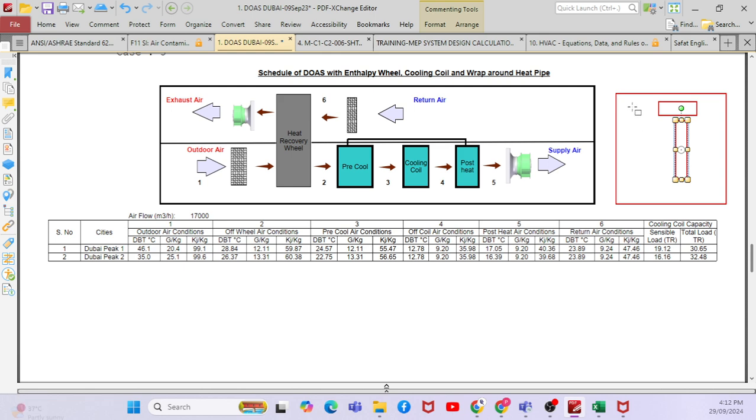Clear, right? Now I'm going to take out some of the air and supply fresh air. So to maintain indoor air quality, I'm going to take out some air by means of exhaust, and I'm going to supply some fresh air. This fresh air should be equal to the room temperature, because I'm not going to supply this fresh air for the cooling purpose. I'm going to supply this air for the replacement purpose, for whatever exhaust I have taken out to maintain indoor air quality. So I'm going to maintain the room temperature, which is 24 degrees Celsius.